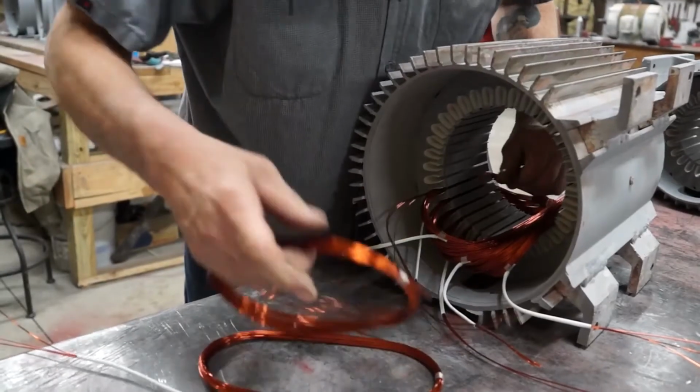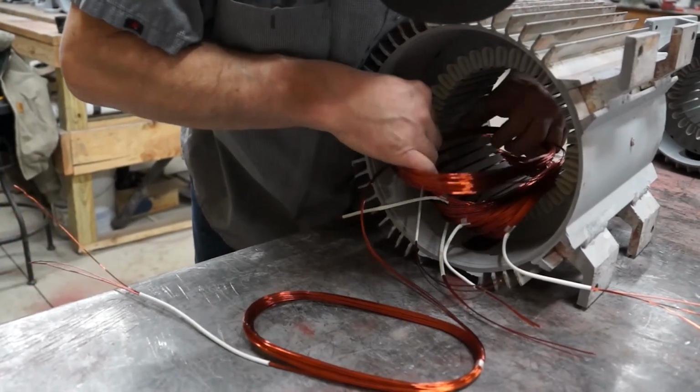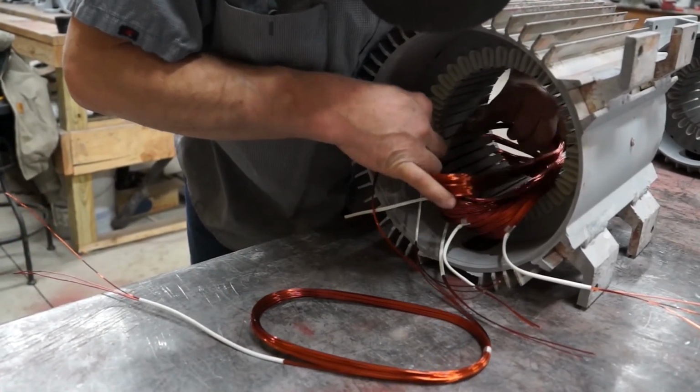But why do we use AC induction motors in the industry? AC induction motors are low cost, they have less maintenance and they have a very rugged construction. There are 2 types of AC induction motors. The first one is the squirrel cage motor and the second one is the slip ring motor. Both are constructed the same way. An AC motor is made up of 3 parts. The first one is the enclosure, second one is the stator and the third one is the rotor. The stator is the stationary part and the rotor is the rotating part.